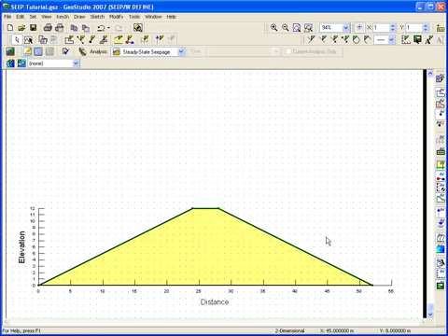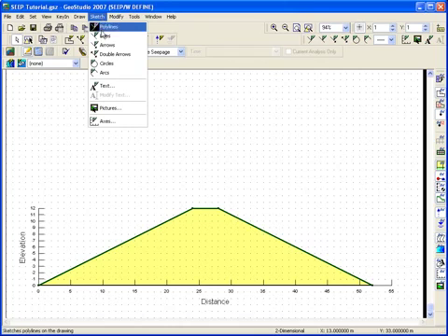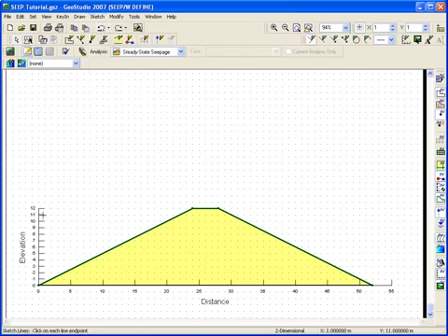Boundary conditions are created and assigned in the same way materials are. Sometimes it can be helpful to sketch additional information on your geometry so you know where to define your boundary conditions. The reservoir level for this analysis is going to be at an elevation of 11 meters.